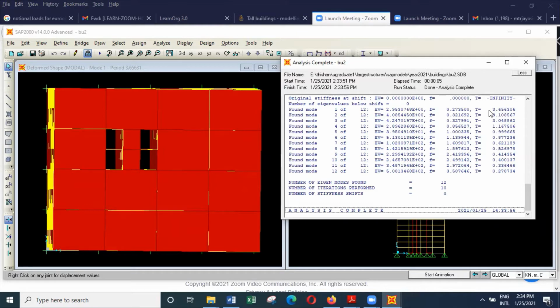The general rule for natural period of vibration is 0.1 seconds per floor. Did you know that rule? Generally, the natural period of vibration is about 0.1 seconds per floor. That's a general rule. Have you come across that rule? Yes, sir. We studied this semester. Sujiva sir taught. Yeah. So that is about 0.1.